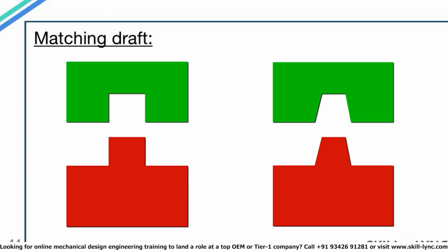The rubbing of core and cavity blocks is an even bigger issue, and the rubbing of core cavity blocks won't happen in all of the models. But in the models where it does occur, like the model which we are discussing, we need to have at least 7 degrees of inclination so that the steel blocks don't rub against each other.